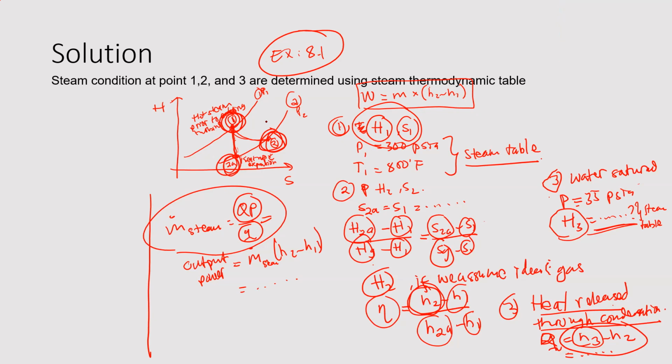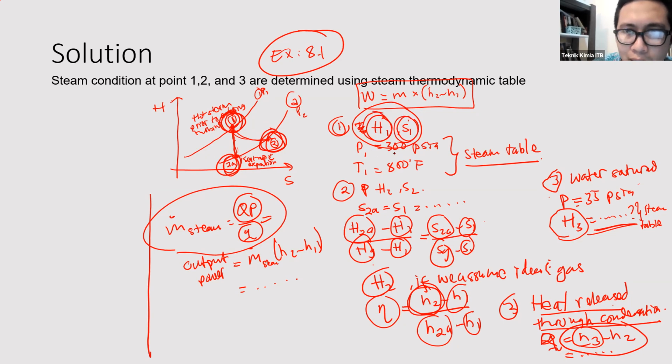Okay, sir. So what you will be given is 0.1, right? So 0.2 won't be given, right? I'm confused. Yeah. So the H1 and S1 you get from the steam table. Have a look through the operating conditions, which is 300 psi absolute pressure and 800 degrees Fahrenheit of temperature. While the H2 and S2, you can calculate based on this formula.